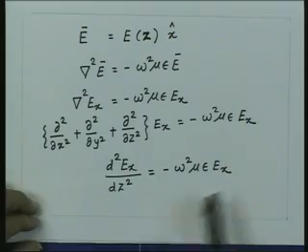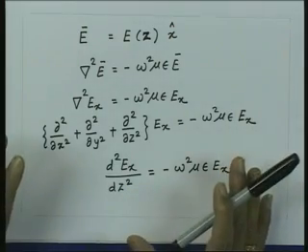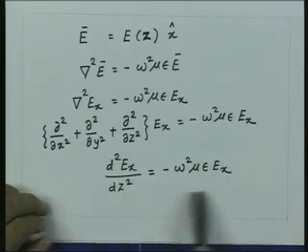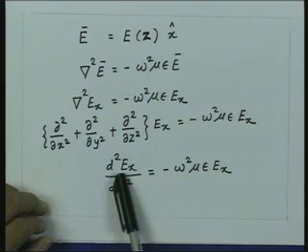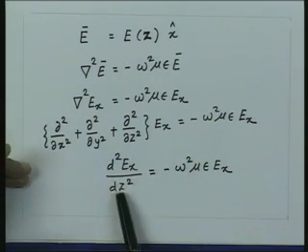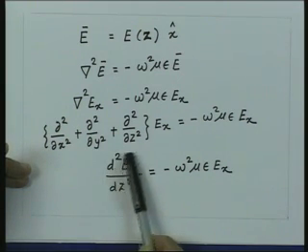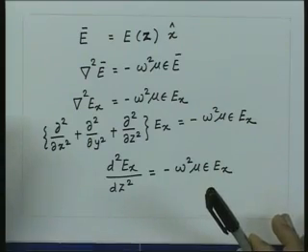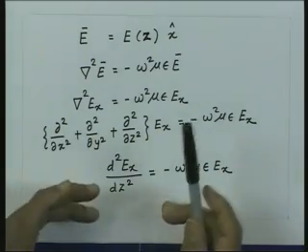This equation now is identical to the equation which we had got for transmission line, because this is now a one dimensional case. We are simply saying this quantity Ex is a scalar quantity, with a second derivative in space, which is what we used to get for transmission lines. So, if I replace Ex by V, I get the equation for transmission line.